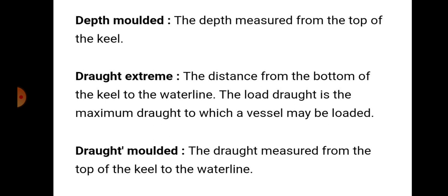The load draft is the maximum draft to which the vessel may be loaded. Draft molded. The draft measured from the top of the keel to the water line is known as draft molded.